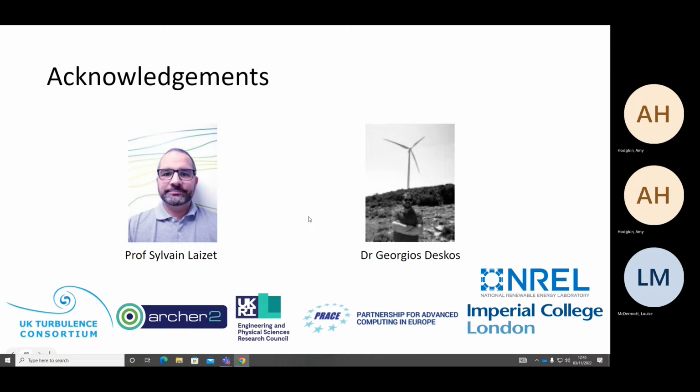And then also, as I mentioned very briefly, this dynamic pitch control is part of this new set of active wake control, where they're trying to actually control the wake so that the wake breaks up sooner. So if we can get the wakes to recover quicker, then by the time the wake reaches the next turbine, there's more energy in the air. But I'm looking at this from a very aerodynamic perspective. There are problems with fatigue when you have blades on your turbine rotating and things like that. So there's a lot of things to consider.